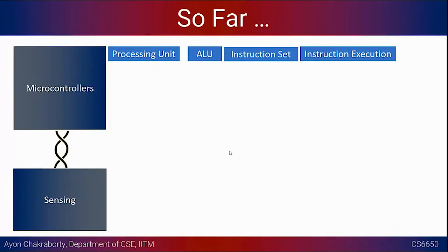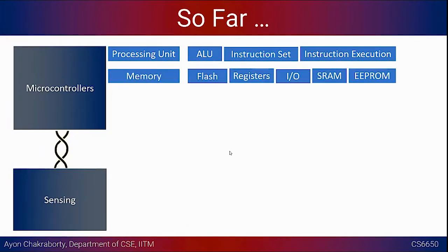After that, we looked at memory from the perspective of a microcontroller, where code is stored: the SRAM, and the bootloader stored in the flash, along with the application binary that you are actually loading. We also covered the CPU registers and the input-output registers, and how they can be programmed to control the different ports, the general purpose input-output pins. So we had a good idea about handling memory, right? Particularly in our case, we will require the registers and the input-output, because we have to talk to a lot of different peripherals, and for that this becomes more and more important.